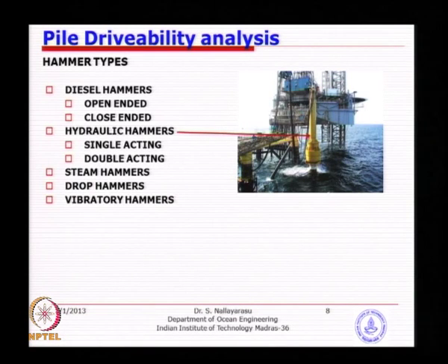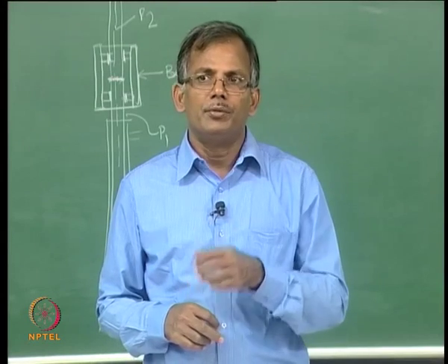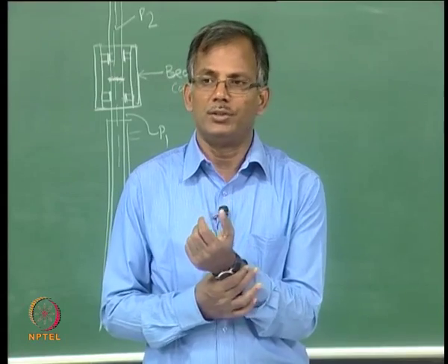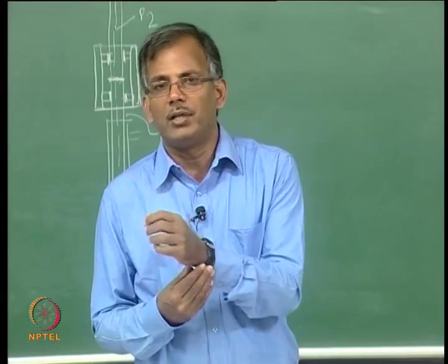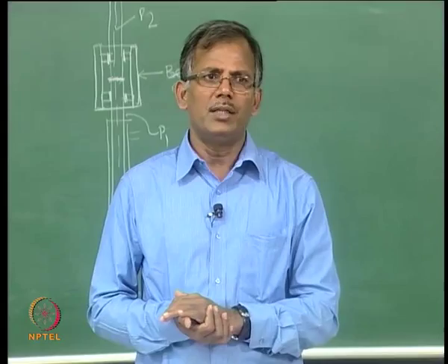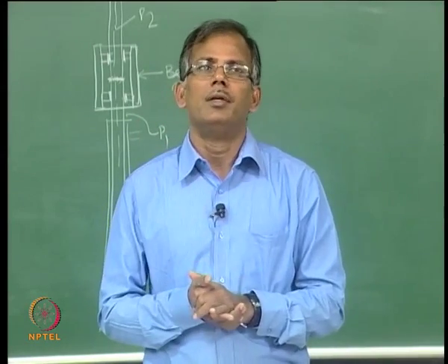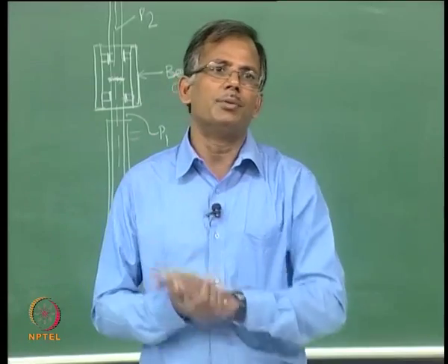Now, in olden days, we used to have pile driving formulas. I think if you have studied foundation engineering, they might have taught you in soil mechanics or foundation classes. A pile driving formula is nothing but an empirical formula derived from the fundamental basics of input energy and energy absorbed.